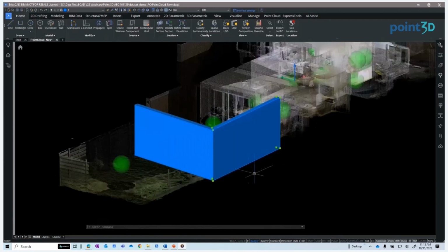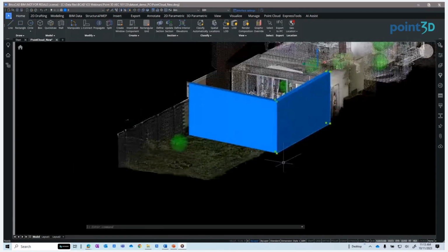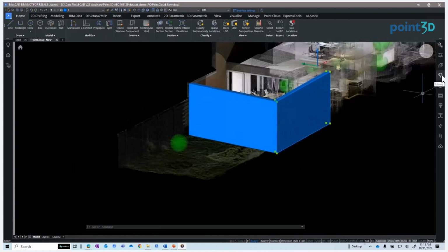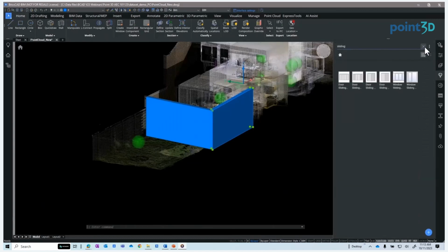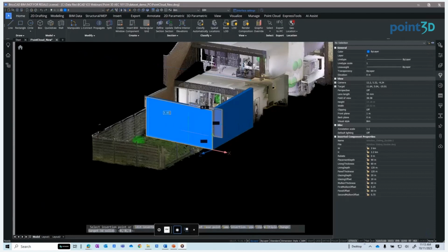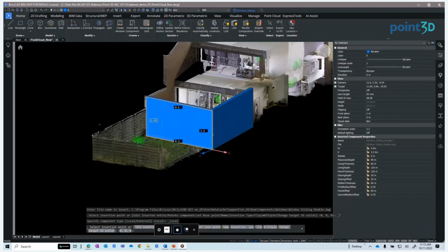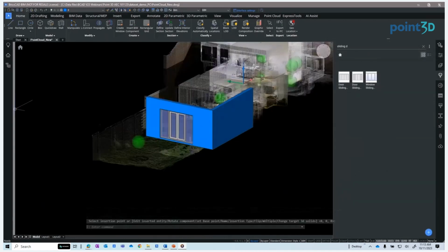However, door and window blocks can be inserted into the PolySolid from the library panel. Simply drag and drop the blocks from the library right into the model. You can use exact values for the insertion point, or as you're going to see what I'm going to do, I'm just going to eyeball it and drag it right over there. Now, these doors and windows are included in BricsCAD, and you can also create your own as well. We're going to look at these in a little bit more detail in the next example.